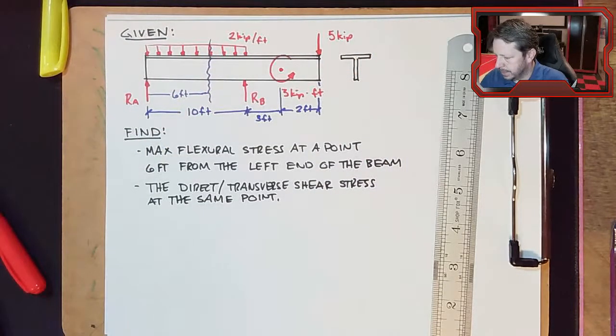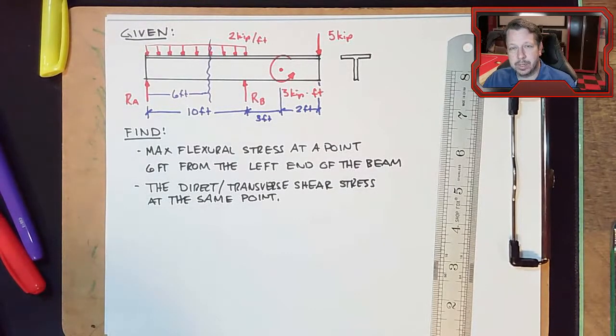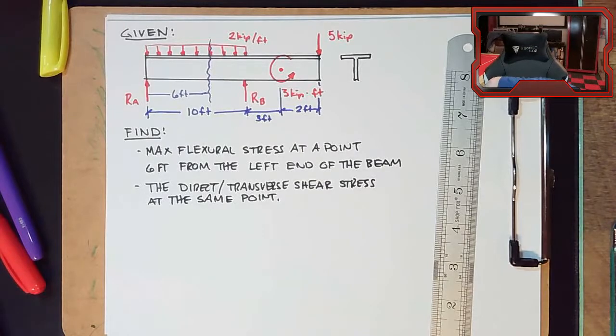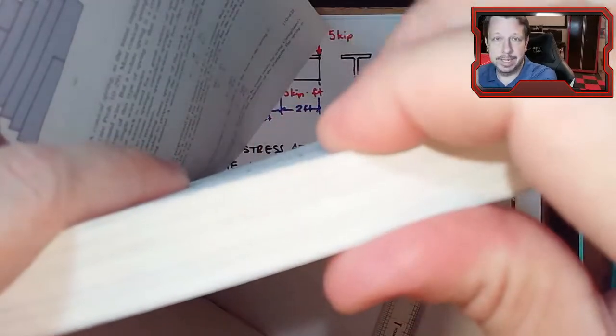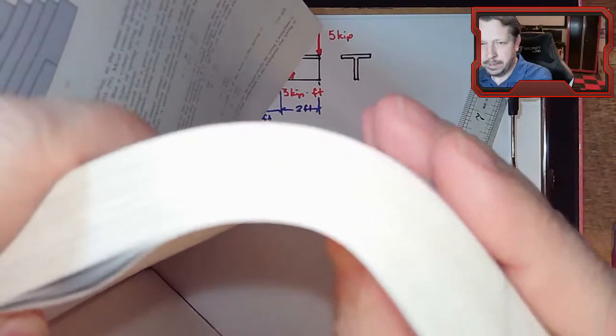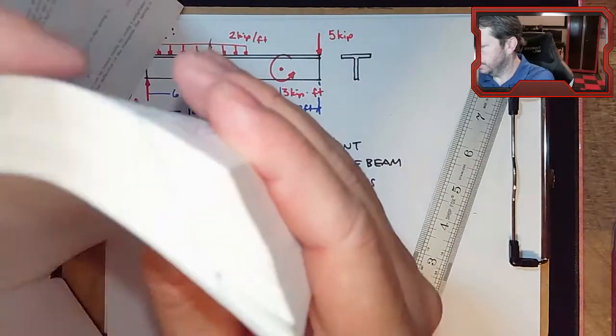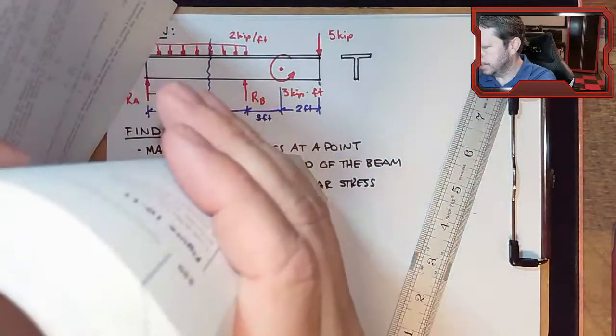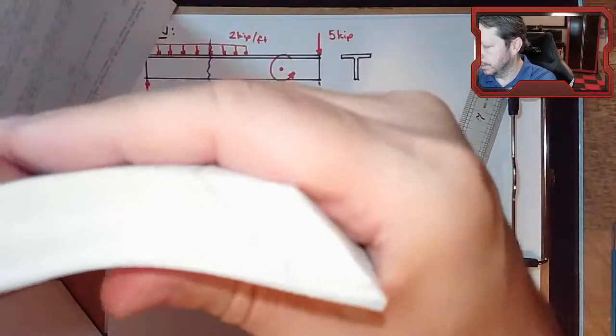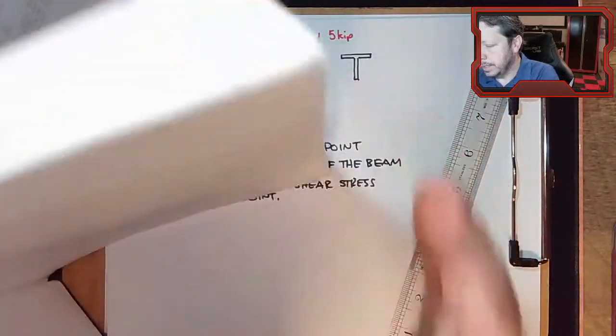But there is another shear stress, kind of like if you think of the pages in a book and you bend the book, all of the pages want to slide past one another. I don't have a nice thick book handy. Oh, maybe I do. Here's a big book. So we take a section of the pages and imagine these are all little individual layers of a beam, but they're bound together because they're part of a beam. When I bend these, if you notice the end, and I know it's kind of blurry, but I don't want to refocus on this, the end kind of gets this curve because all of these pages are actually sliding past one another. That sliding past one another is a shear stress, and so there is a shear stress between the layers of the beam, if you think of the beam in layers, that we might also want to calculate.